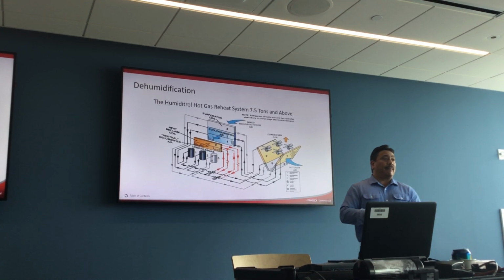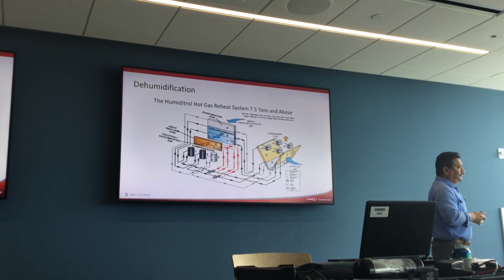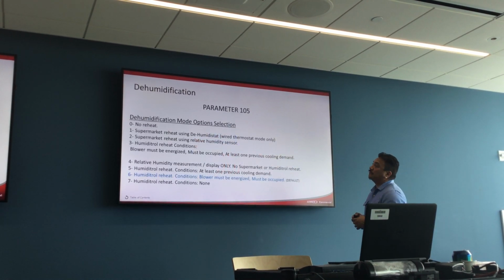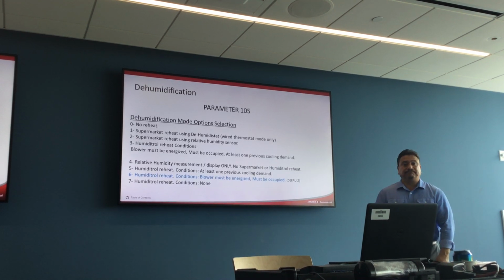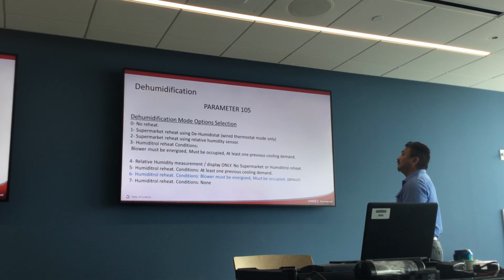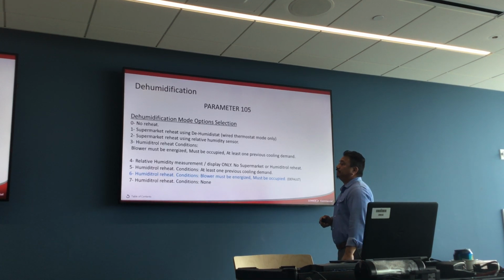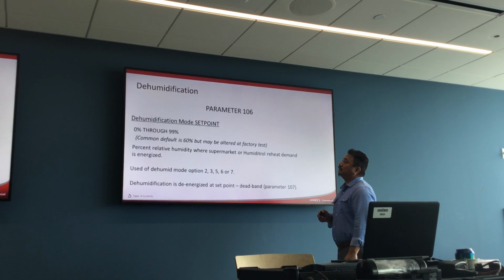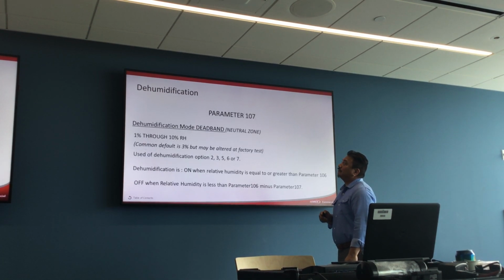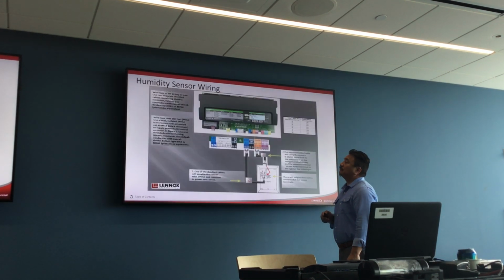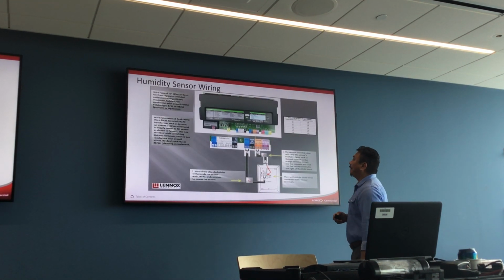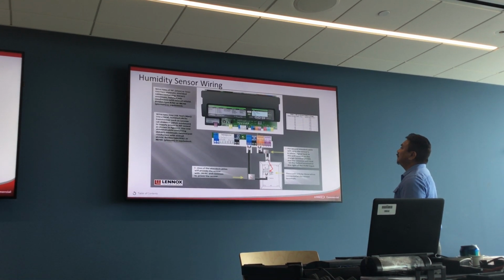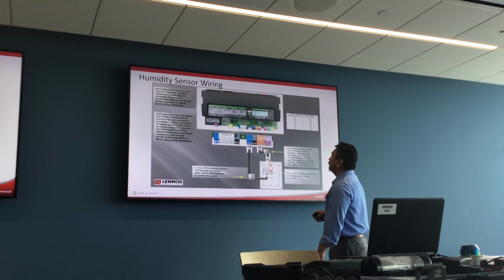One thing we're hearing from Autumn, your project manager that reports to Dave and installs the units for us, is that if you're replacing a Carrier 5-ton unit or something, just the stock, basic core and shell unit, no bells and whistles, the Energins unit weighs a lot more than that unit. And so our contractors are requiring an engineering study, and maybe those roofs aren't load tested for a piece of equipment that heavy. So it's something we still need to work through, but it's hard to replace that hefty of a unit when there's something so basic in place without going through some engineering changes.